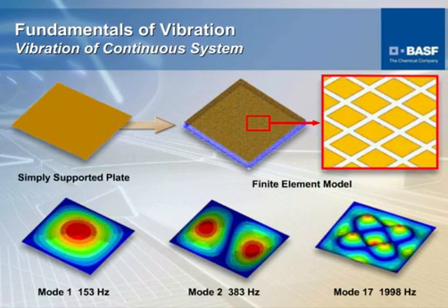Natural frequency system or characteristic can be extracted by doing a simple finite element analysis model. Essentially, the structure, which is represented here by a supported plate, is depicted in a finite element model where the surface of that structure is subdivided into elemental parts and represented mathematically within a certain code with the proper stiffness information. Then the input parameters would represent what a free vibration system would do and what those amplitudes would be. There are ways, mathematical ways in every code or simulation code that exists today where you can get natural frequencies of the system by doing simple equations.